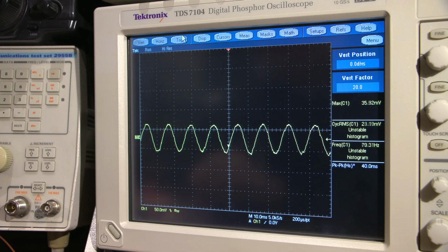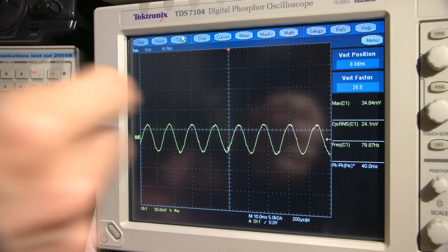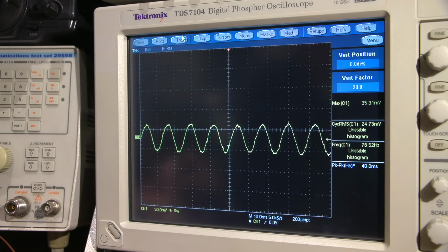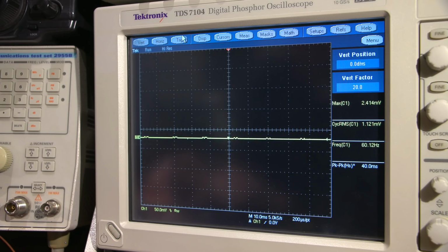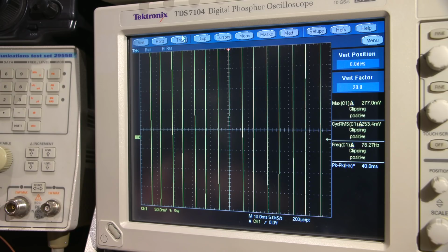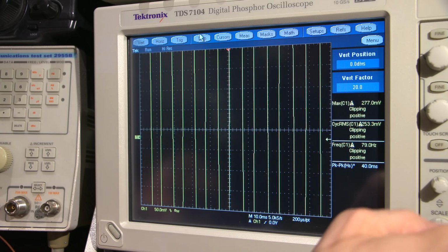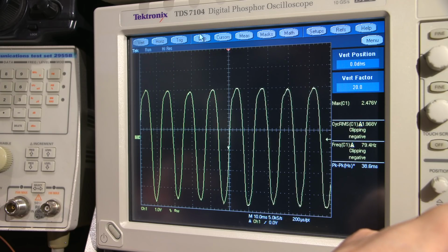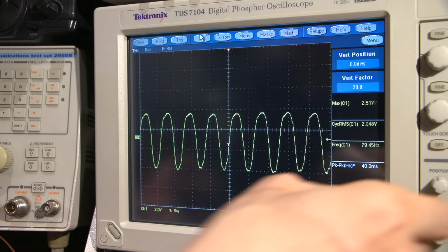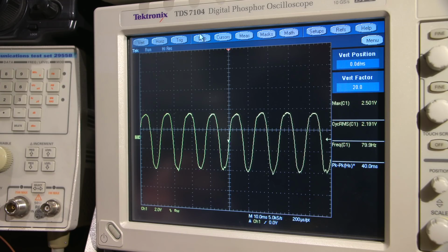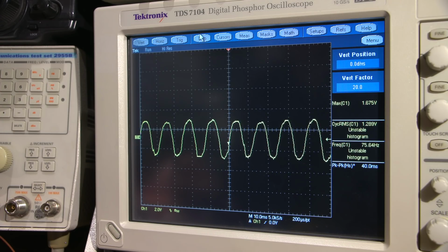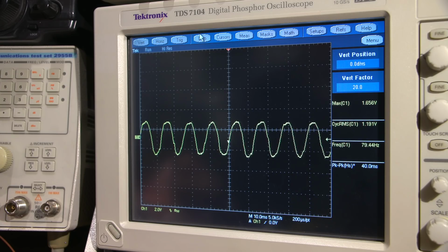So now we're going to go to test point number 7, and again, if this stage is working, we're going to see the amplitude raise up. And now you can see why you wouldn't even need an oscilloscope with any kind of even a graticule for this. Look at how much gain there is there. Let's move this out of the way. I have to turn this way down. So you can see lots of gain there, and that's at 2 volts per division. So you can see like we're actually overdriving it just a little bit. So I can turn this down, and you can see the sine wave cleans up with a bit of noise there, right? So again, any older type of oscilloscope, even that old Heathkit scope that I did the restoration on, would be just absolutely fine for this.